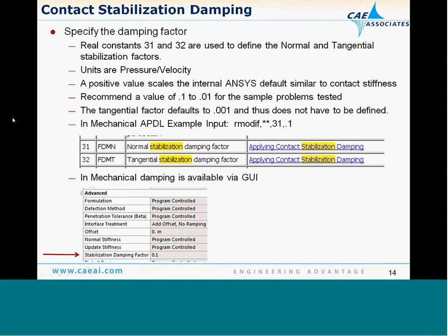Adjusting the contact stiffness, increasing the number of substeps, sometimes refining the mesh can be an effective tool, because we can create more contact elements on the particular interface. And then the feature of course, including contact stabilization, maybe the next time we take this poll, a few months after people have tried this new feature, we may see people adopting that as well.